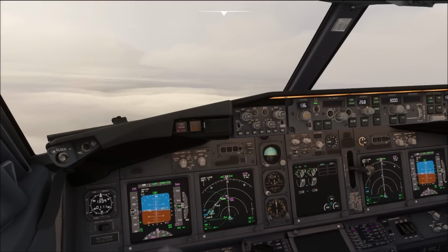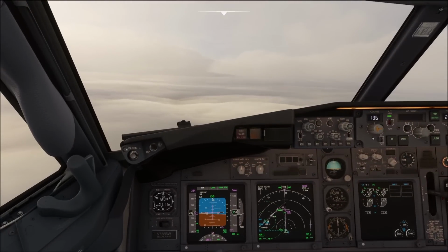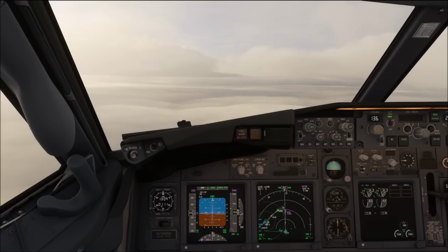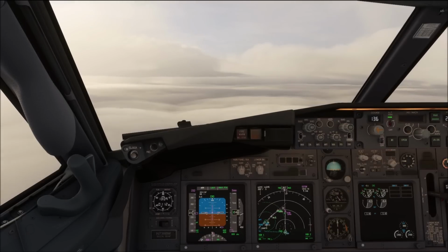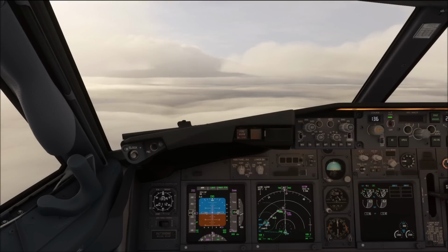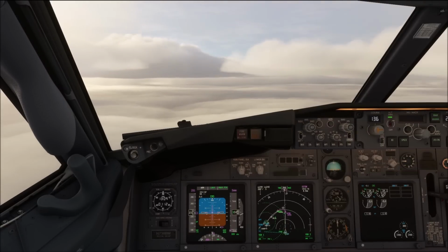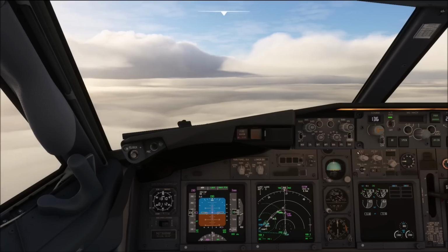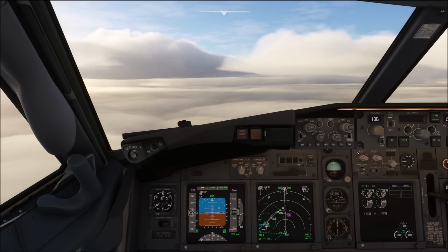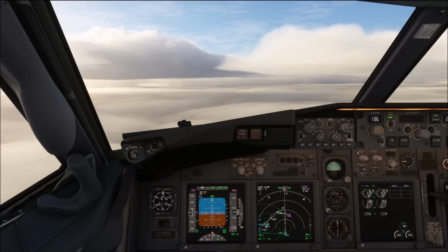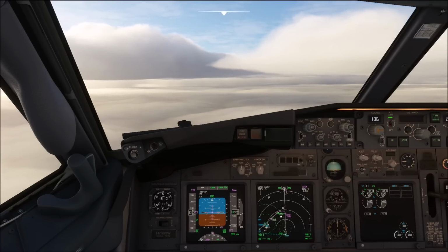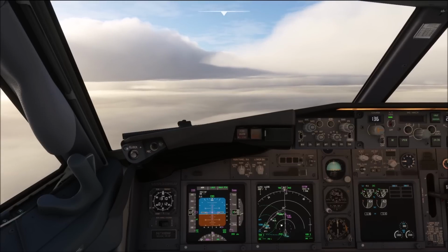So there is no phraseology published for that, so I would, for example, just say: PMDG 738, in case of missed approach, we will climb to an altitude of 3,300 feet due to cold temperature corrections. That is something that controllers online may or may not understand, but it is very important that we do consider this. The next thing that is important for us, however, is when to use anti-ice on the descent.